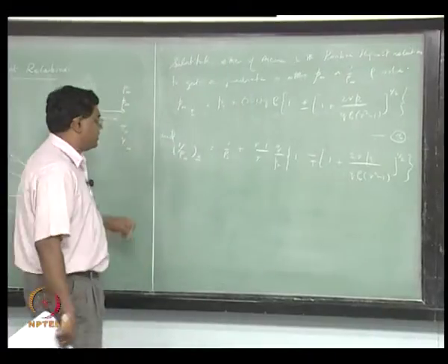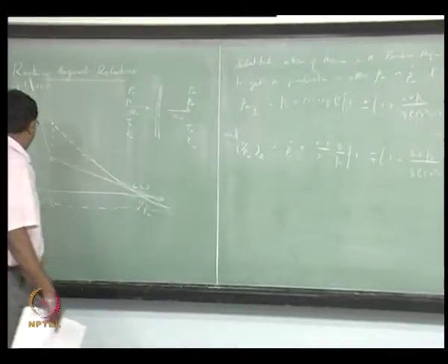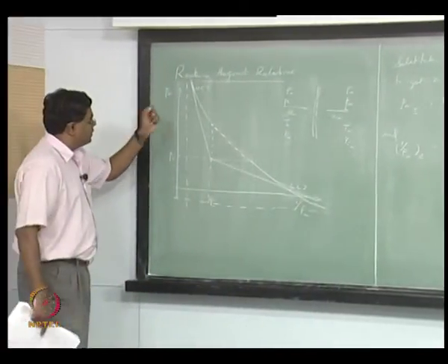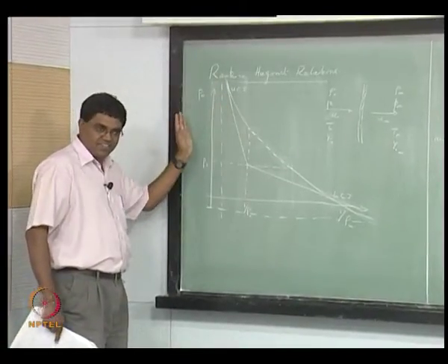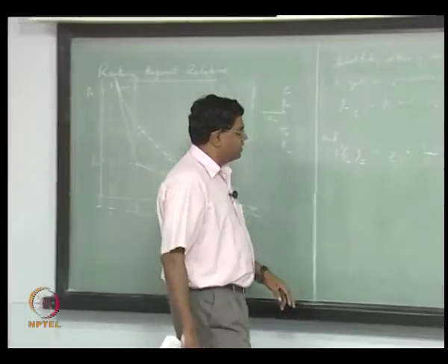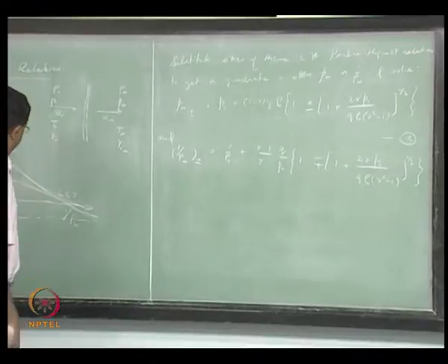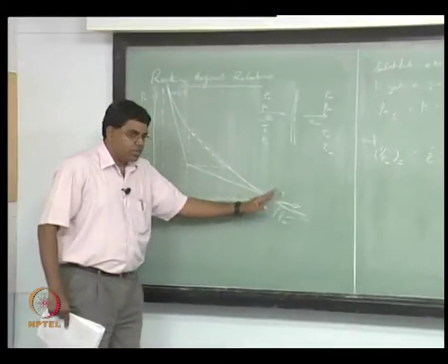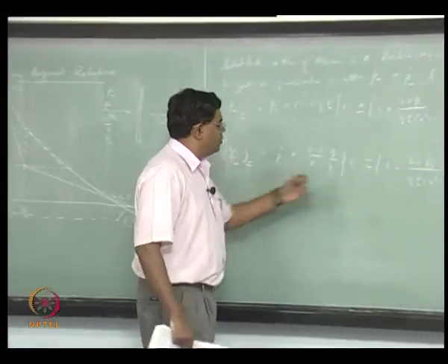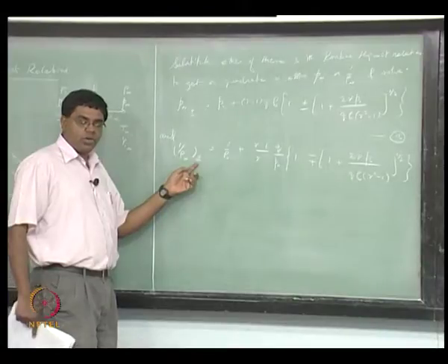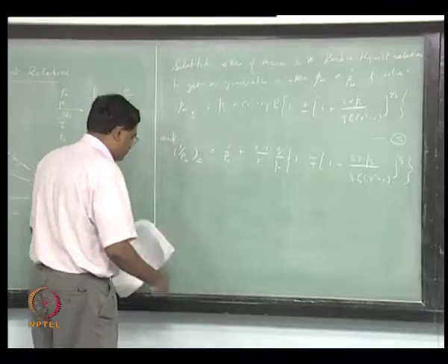And similarly for 1 over rho infinity, for the upper Cj you need to have a 1 over rho infinity that is less, therefore you need a negative sign over there, and for the deflagration Cj point, the LCj point, 1 over rho infinity is greater, therefore you need a plus. So the lower sign will always correspond to a LCj, upper sign corresponds to a UCj, right.